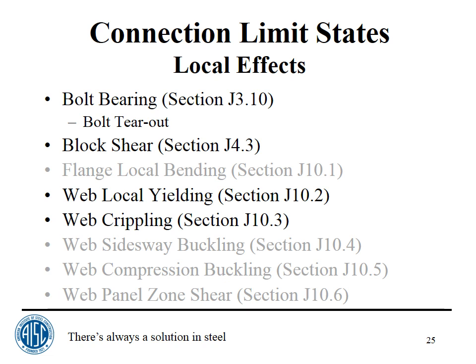Bolt bearing. There's really two requirements in bearing. One is bearing, and the other one, which is still in the bearing section, J3.10, is called bolt tear-out. I prefer to call them different limit states because they really are, but the specification, even the 14th edition specification, calls both of these bearing. Block shear,